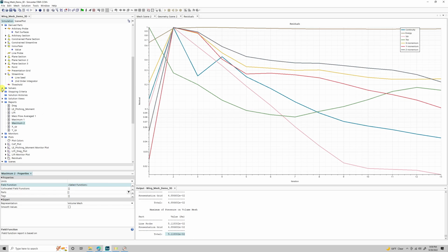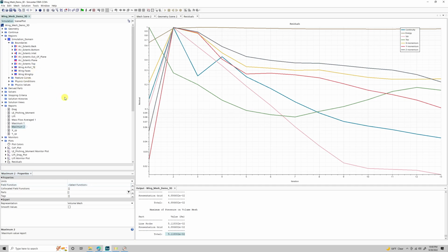After it's done with that, it throws out the value for every cell. It doesn't need to remember the residual value for every cell. It already summed them up and gave you an overall value. It got rid of what it used to do that, because that's memory it can use for something else. That's all well and good, except if you want to know exactly where the residuals are high. If you want to know where the residuals happen to be higher, then you need to know what cells have what residual value.